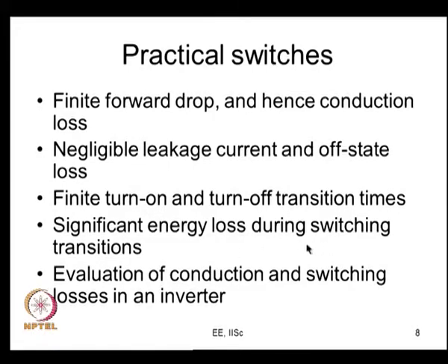Similarly, when the device is turning off, it takes a finite amount of time. So, during turning off, what do you expect? You expect the current to fall and then the voltage to rise. Before the current has fallen, the voltage rises. So, there is significant amount of both V across the device and current through the device during such a transition. That leads to a certain amount of power dissipation, and there is an energy loss over the switching interval. You call that switching energy loss. So, there is a significant amount of energy that is lost during turn on and turn off.